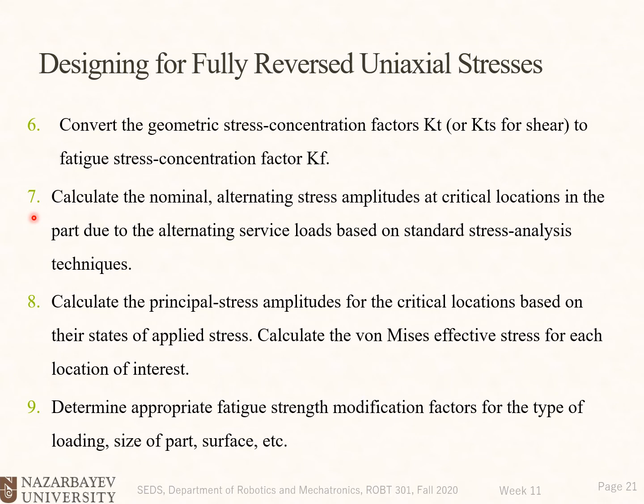Okay, so what you need to do, you need to find the nominal loads, nominal stresses. 8. Calculate the principal stress amplitudes for the critical locations based on their stresses of applied stress. Calculate the von Mises effective stress for each location of interest. So you need to calculate the Mohr's circle and, based on that, the principal stresses and the von Mises stresses.